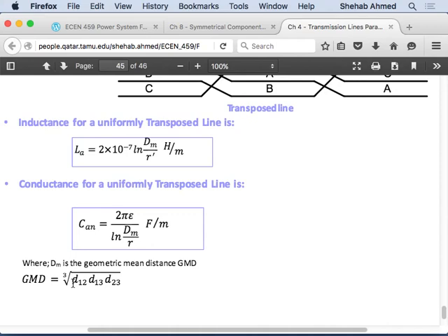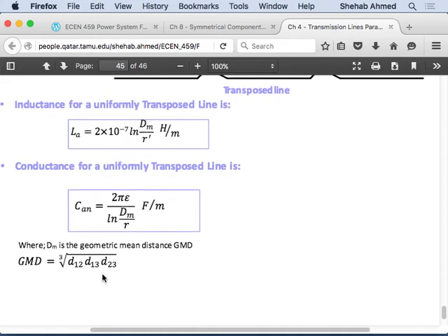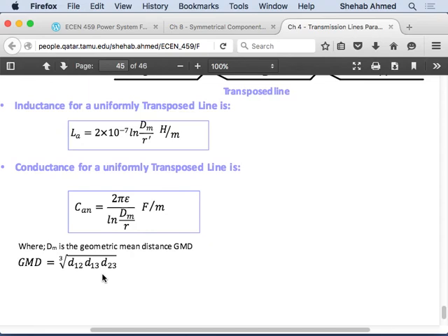In the equation that you applied now, it's the same D. But where does it come from? It comes from this equation. Yes? But all the small d's are the same. If they're all the same, then it's D cubed. Cube root of D cubed is D, right? So it's what we had before. It's the same D. If they're not the same, then use the actual distances, take the cube root, and use that D in the equation that we just applied.